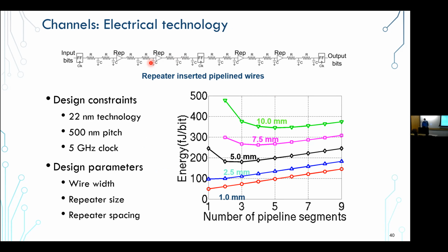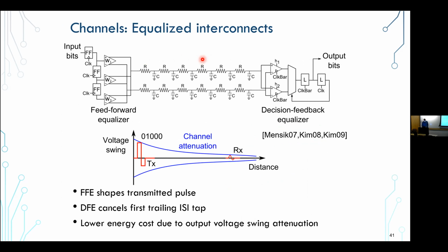We could build sense-amp-based flip-flops that recover the low swing into high swing. So there's a whole spectrum of techniques you can use to lower the energy on the channel for given throughput requirements, right? It's not just repeaters versus equalized, but there's low swing, etc. Those are the kinds of things people are considering.